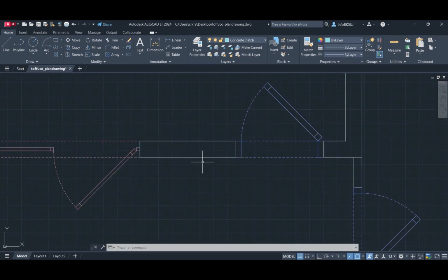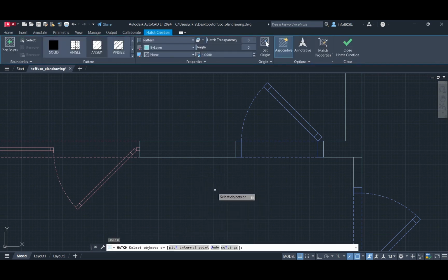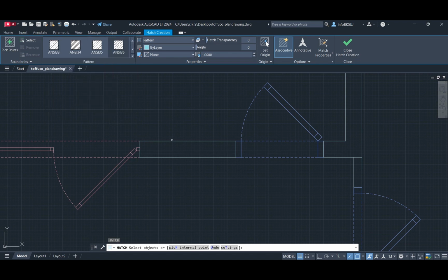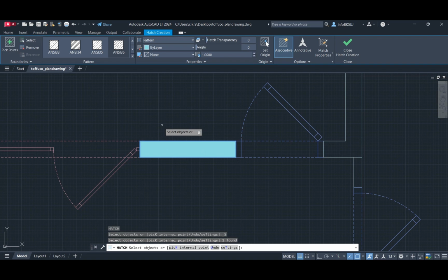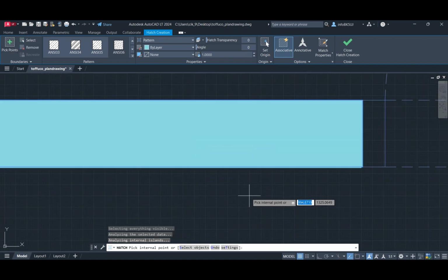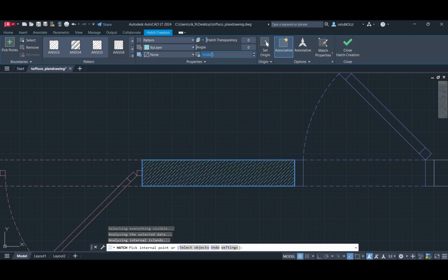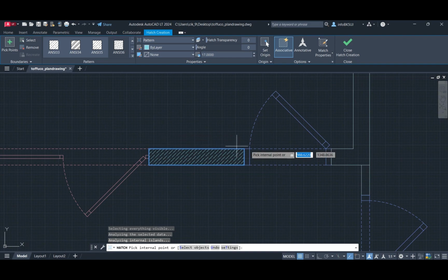After putting the windows in their places on the plan, hatch the walls using the Hatch command with the appropriate hatch according to the material of our building. You can select the areas to hatch with the Pick Points or Select Objects options. After selecting the hatch you want, you can scale the hatch according to the plan scale you draw.